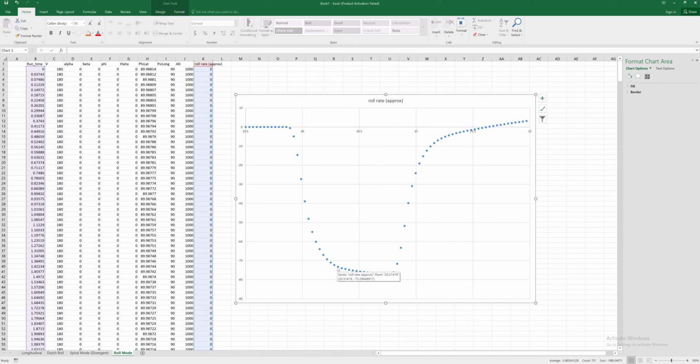And so that's why pilots associate a change in aileron deflection with a constant rolling rate. To them, it almost feels instantaneous. When they deflect the ailerons, they begin rolling at a constant rolling rate. And they don't notice this transient because it's so short and so heavily damped.